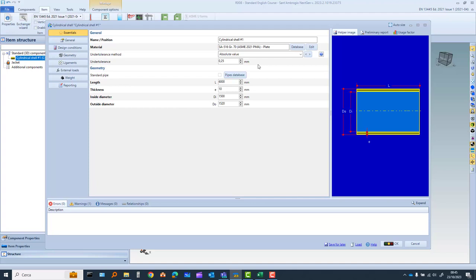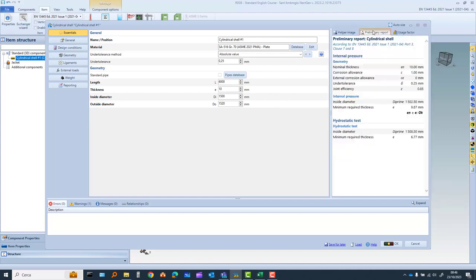It is necessary, therefore, to place an order with a manufacturer specifying the ASME standard with an additional requirement. The additional requirement is the guarantee of the hot yield strength at the design temperature. Well, let's check what happens here using the ASME material with the harmonized pressure vessel standard.